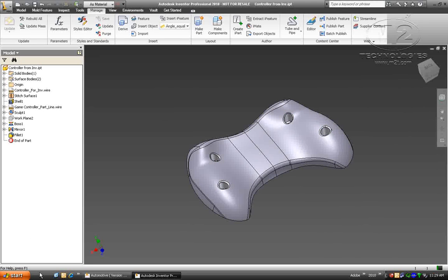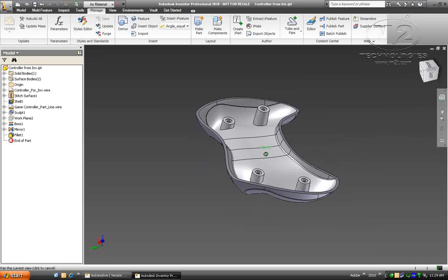And if there are of course more features down the road, you always want to start at the top, fix from the top, and let it filter down, because other features rely on the original features. So you always, when you fix a model, want to start at the top, and things start to then fix themselves down the feature tree.